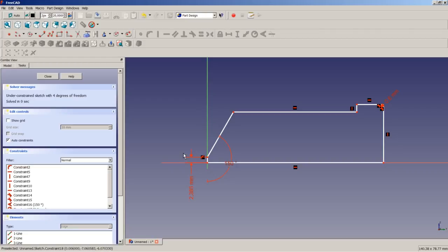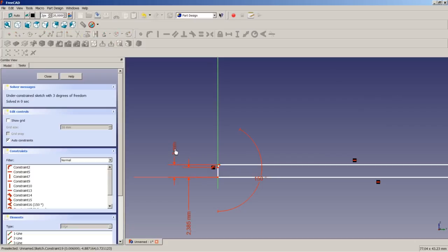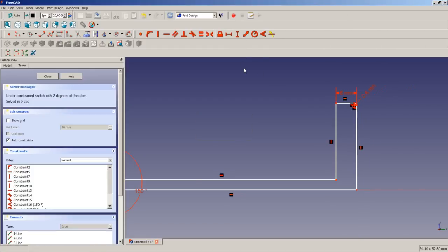I did look in the instructions for the metric threads before creating this tutorial, so I looked up the values of all dimensions to be able to create real dimensions like this one here. So now we apply to these 2 points a vertical dimension constraint of 3 millimeters, since we want to do in this case a thread of 6 millimeters. I will also apply an 8 to the head of the screw of 6 millimeters.